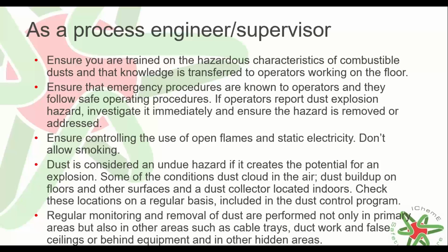Ensure that you are trained on the hazardous characteristics of combustible dust, and that knowledge is transferred to operators working on the floor. Ensure that emergency procedures are well known to operators and that they follow safe operating procedures. If operators report a dust explosion hazard, investigate it immediately and ensure the hazard is removed or addressed. Ensure controlling the use of open flames and static electricity, and obviously don't allow smoking.